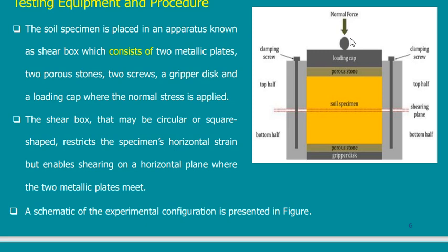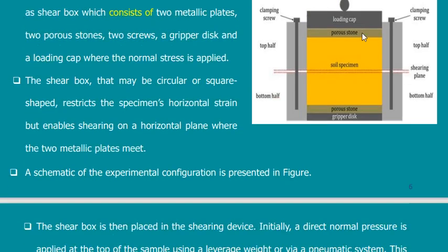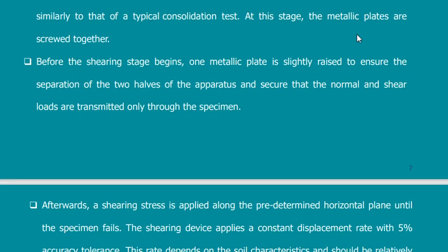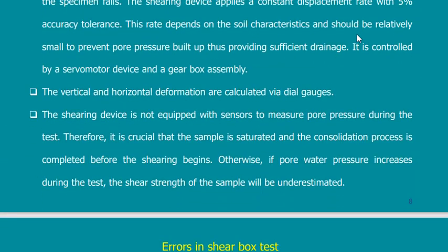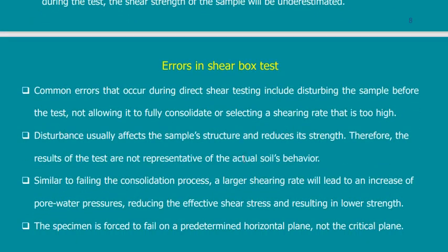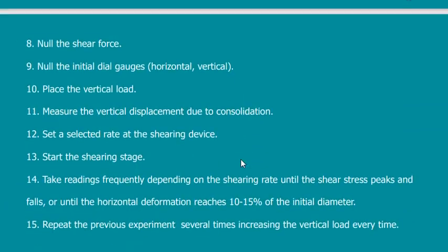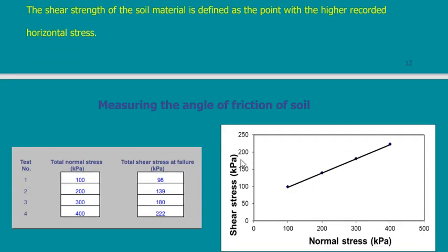Each time I repeat the test, I will get a different load for the shearing value, the value at ultimate that corresponds to the normal force that you are applying. Usually we repeat it 3 times to draw the line. I will just skip this now and then return back to it, but I want to show you how this is how we do the test.